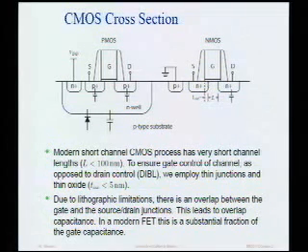Not going to talk about device physics in this course. In terms of high-speed performance, we know, and we'll review that briefly, that using shorter length devices is a big advantage. The shorter we make the channel length, the better. And probably the advances in integrated circuit technology for the past 20, 30 years has all been about making that channel length shorter and shorter through lithographic technology. And in fact, today you can go out there and buy a transistor with 90 nanometer channel length. Actually, the effective channel length is even shorter. It's about 60 nanometers. So we're talking really big channels here.